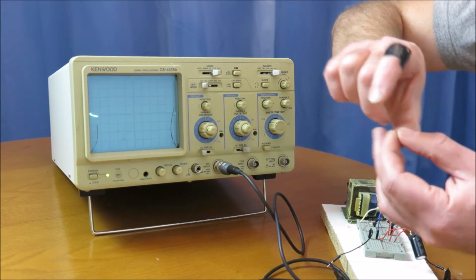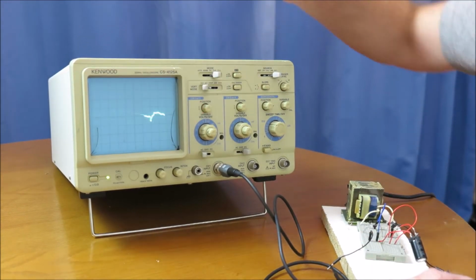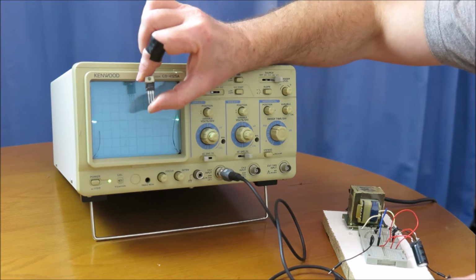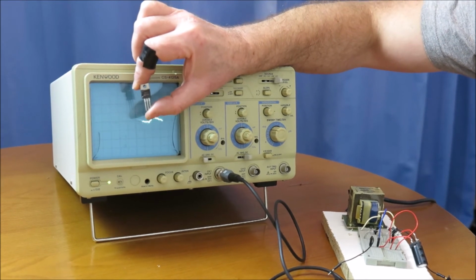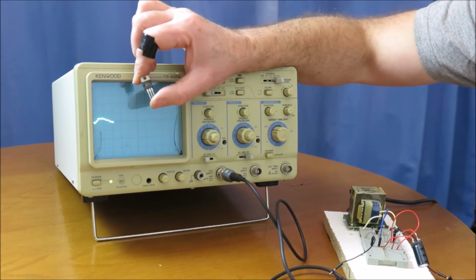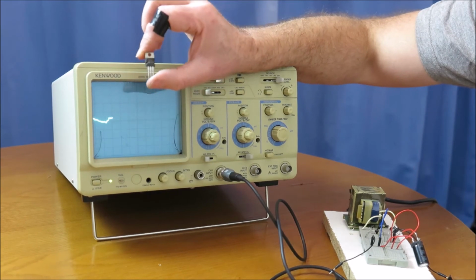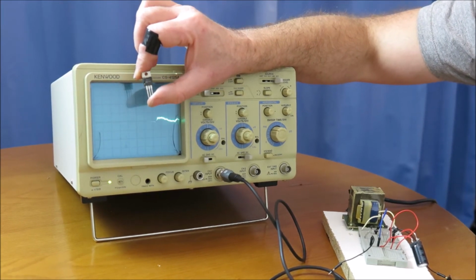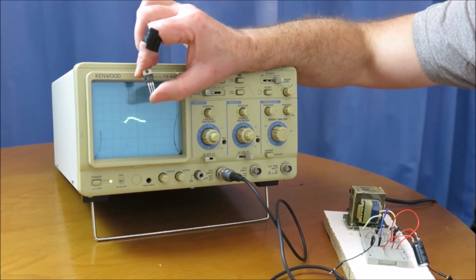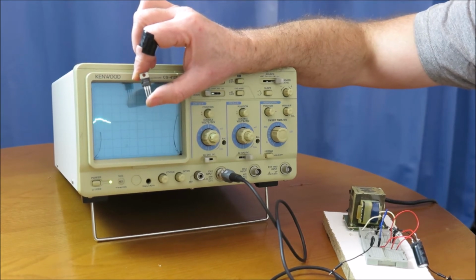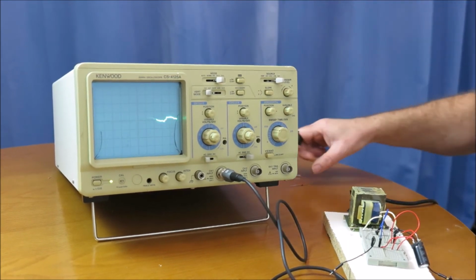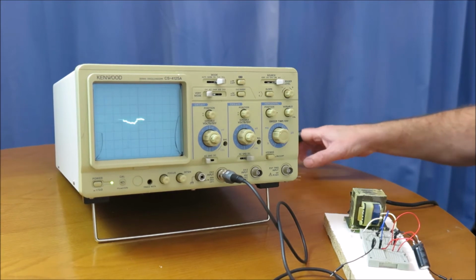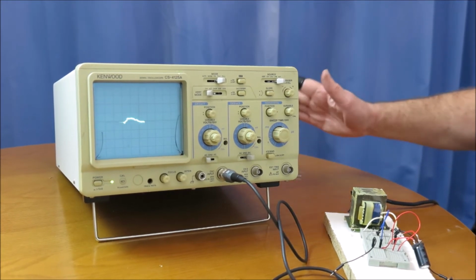So we can either put in a Zener diode like that, or you can have the 3-pin package which will do your voltage regulation for you. So if you wanted a fixed voltage out, you can put one of these regulators in, and then you would have a constant voltage at the output of your supply. So those are the regulation components: the Zener diode and the 3-pin regulator.